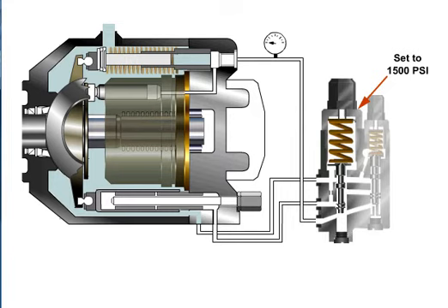This is accomplished by hydraulically positioning the pumping chambers to zero output while maintaining compensator pressure at the outlet of the pump. In this example, we have used a pressure-compensated piston pump. It is helpful to understand the functionality of a piston pump. If you need to review this, return to the Pumps menu and go to the animation for the piston pump.